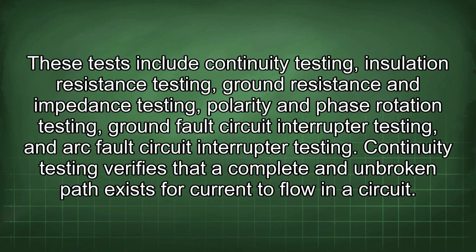These tests include continuity testing, insulation resistance testing, ground resistance and impedance testing, polarity and phase rotation testing, ground fault circuit interrupter testing, and arc fault circuit interrupter testing. Continuity testing verifies that a complete and unbroken path exists for current to flow in a circuit.